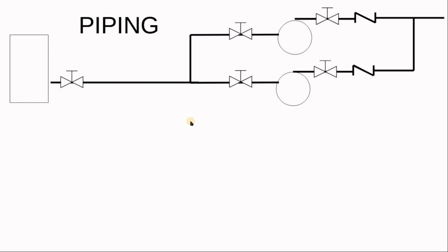You can see now in this drawing, we have two pumps, two redundant pumps, suction and discharge valves. So if you want to run this pump, you close, close, open, open. So pump A, assume this is A, will run, and you close, close, open, open, you run the second one. Because those are manual valves, the transition from pump A to pump B has to be done locally.